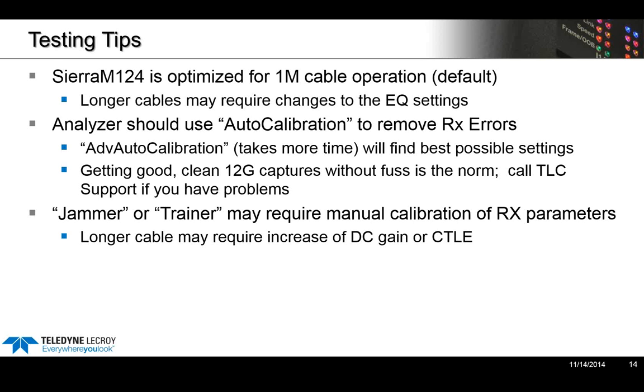Great. So I think you can tell link initialization is a little more complex when you're operating at 12 gigabit. But what about the higher layers at the protocol layer? So SAS 3 is very similar to SAS 2, a lot of the same state machines, same timers, but now we're running twice as fast.